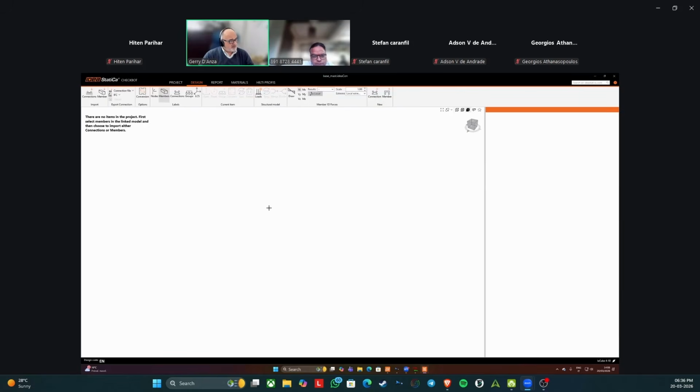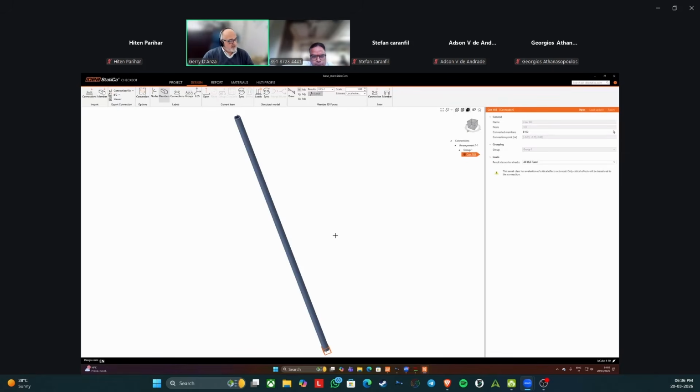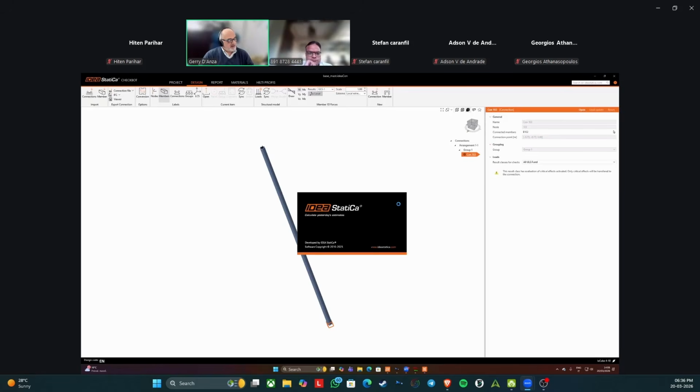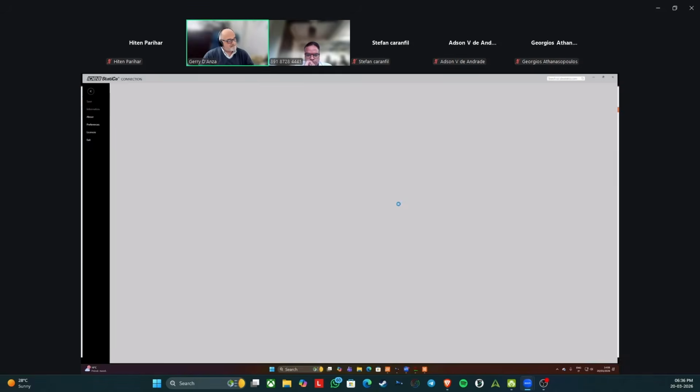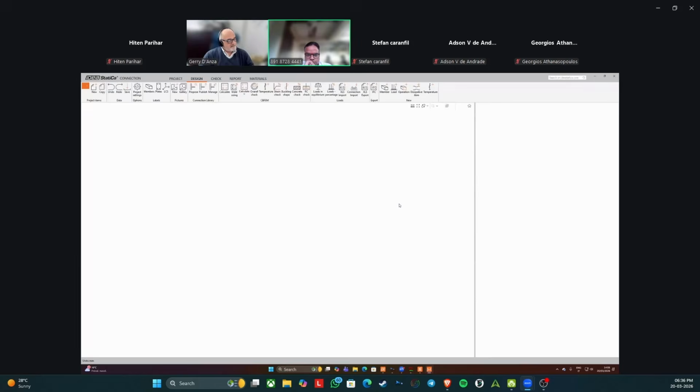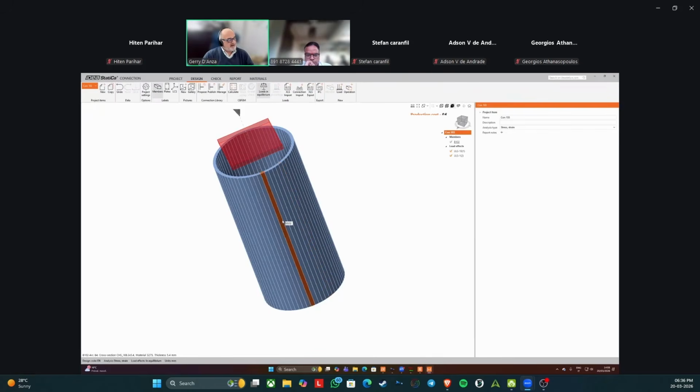So with a new project, now we have to import the node. Remember, we have selected the node inside the FEM software, and you say, I want to make a new connection. So it imports this data, and you see here, this is the node that we have selected. It also imports the elements connected to that node. So if this is what you want to do, you just open this connection node. Okay, and that's it. This is a single pipe, so it's the end of the mast, and that was quite simple. You don't have to do so much. Now the hard work comes in.